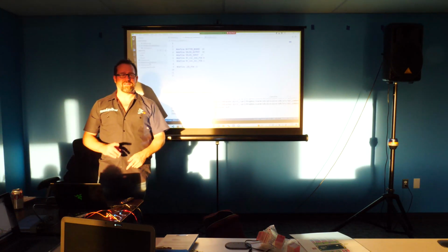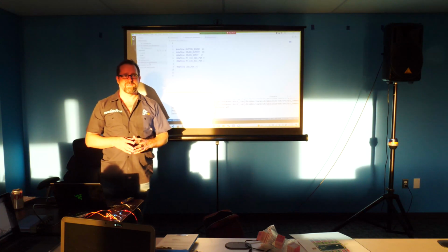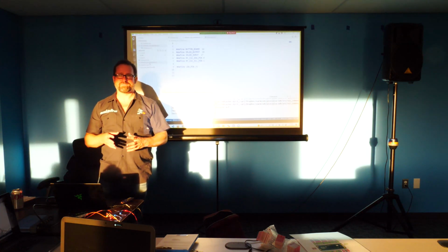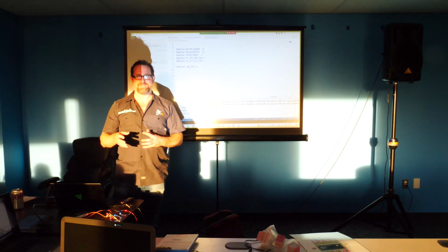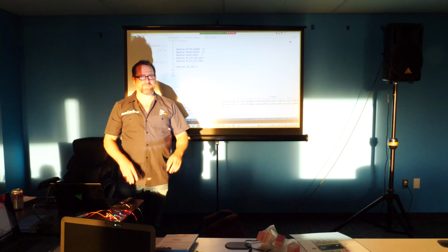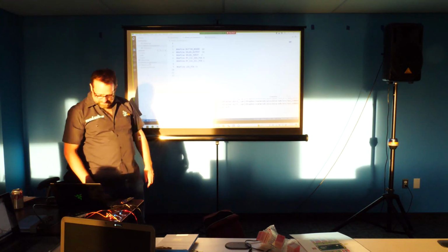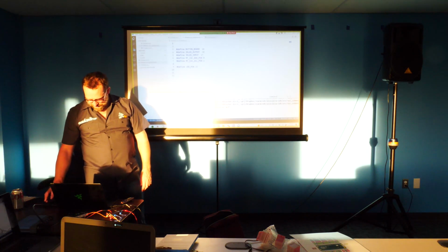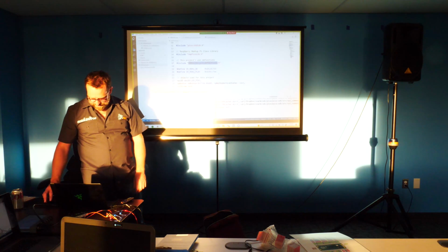A lot of other microcontrollers have a ton of pins, but you can only do certain things on certain pins, which is like when you have a 2,000-page data sheet, you always get caught when you design a board, like, oh, you can't do it on that pin, or that pin's analog. There's all kinds of gotchas, but that's pretty clean how they designed it. So it's just another reason why this part is a lot of fun.